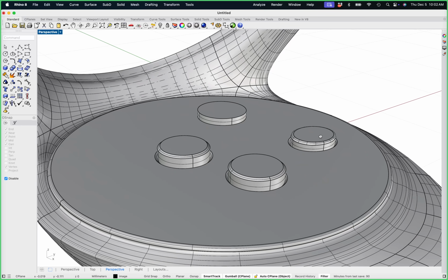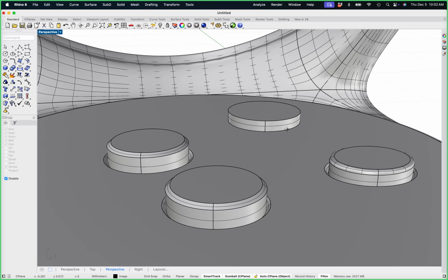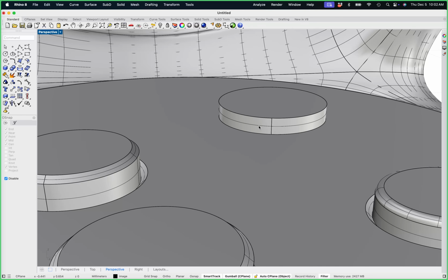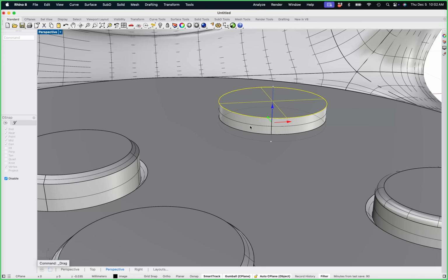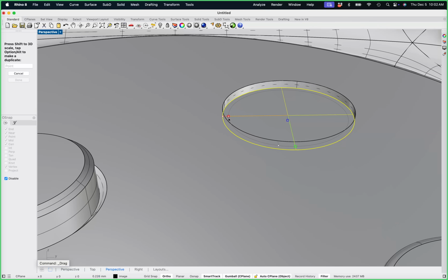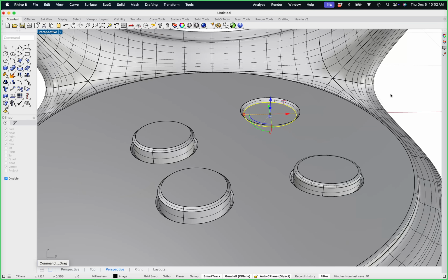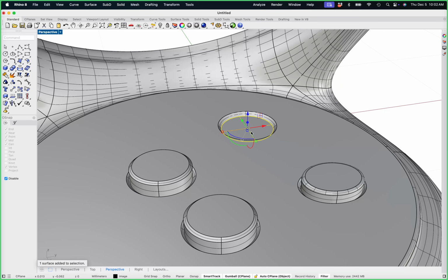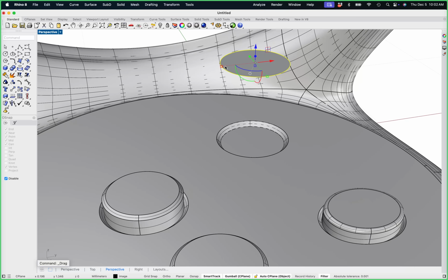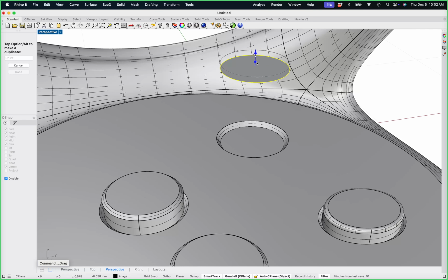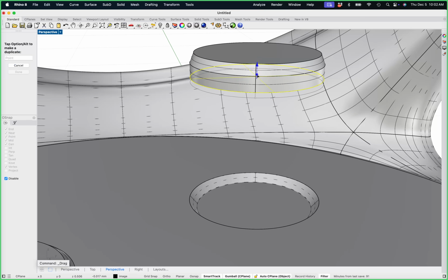And then this little gimbal thing over here, maybe that is a little bit different thing altogether. So maybe we take this and we just make a little chamfer in there. And then maybe what I want to do is steal this, go straight up, tap Alt, and then maybe I want to do this the opposite direction. Maybe I want to start going this way to make an object